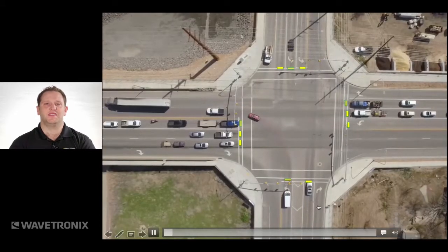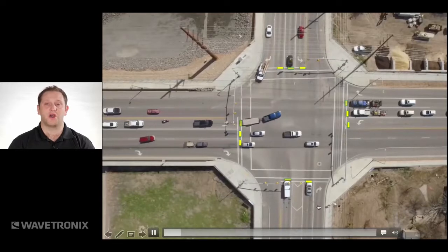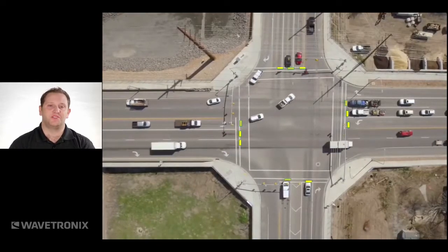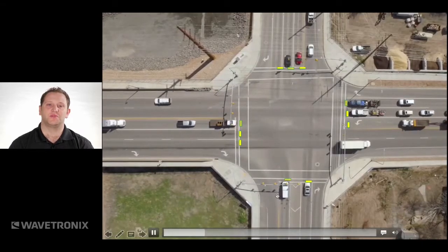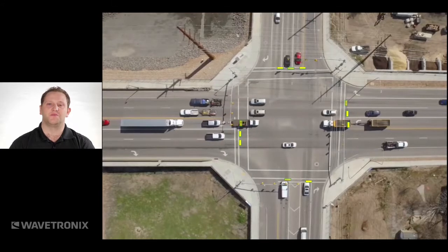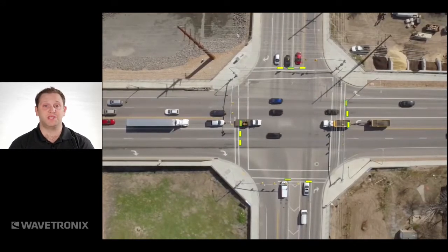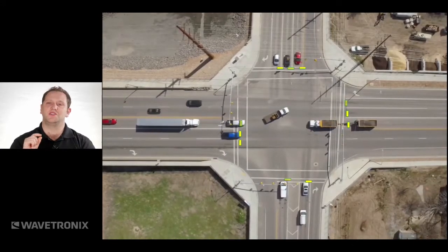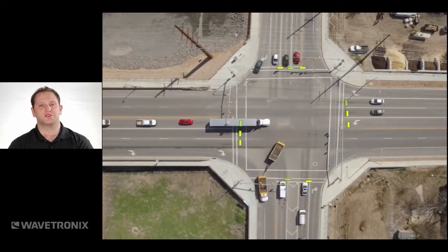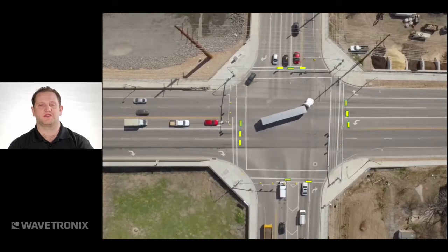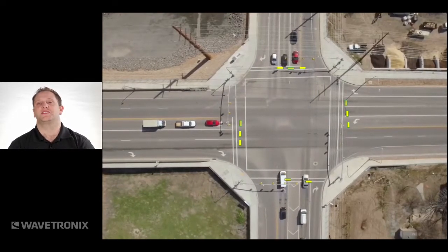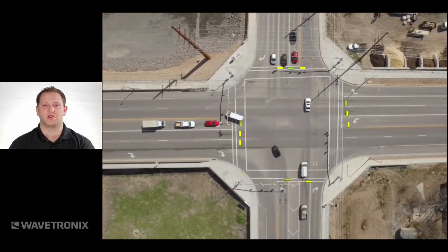So to set up a red light runner monitoring system, or at least count them, you need to place a zone very similar to where you would place a counting zone, just in front of the stop bar. But because we're using radar, we can detect the speed of the vehicle as well. So we can add a little filter and only put a call into the controller, or count the number of cars that go when the speed is faster than, say, 15 or 20 miles an hour.